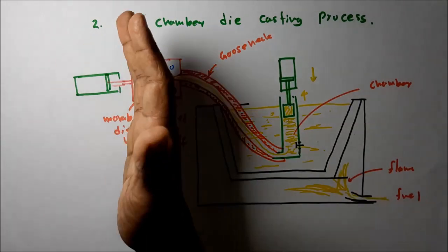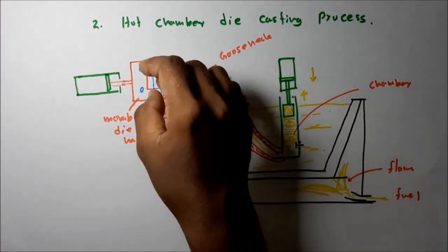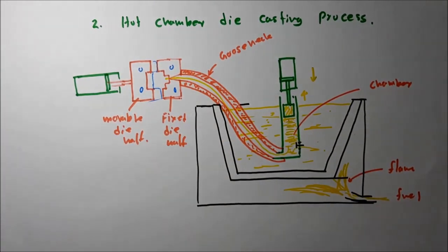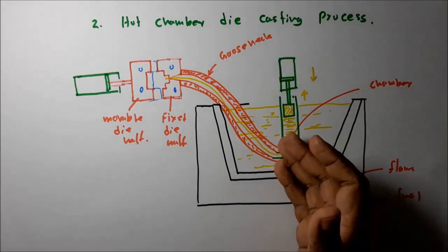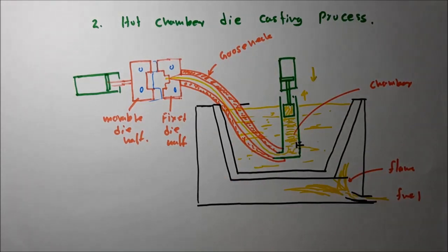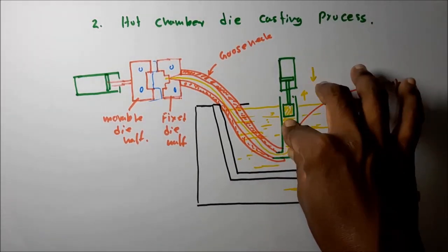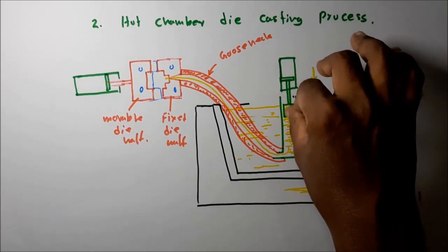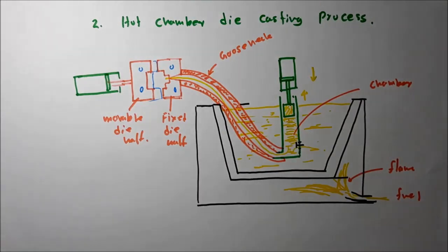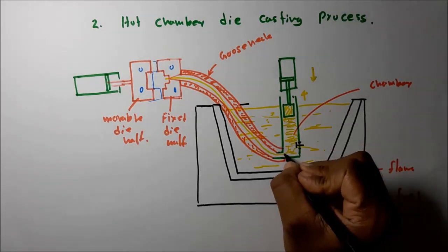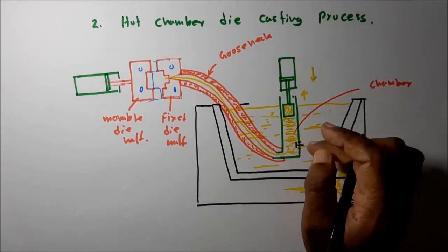So then what happened? The mold is open. After it solidifies, the part can be taken out. Again, this flange moves upwards. Then a certain volume moves into this chamber. Then again the molten metal is injected. Then this is a cyclic process. This is a cyclic process. Two gating systems are also used. This is one of the methods.